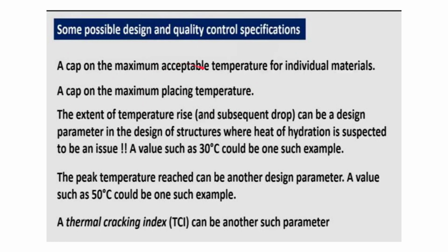A cap on the maximum acceptable temperature for individual materials is necessary. A cap on the maximum placing temperature is also important. The extent of temperature rise and subsequent drop can be a design parameter in the design of structures where heat of hydration is suspected to be an issue, mainly for hot weather concreting. A value such as 30 degrees centigrade could be one such example.